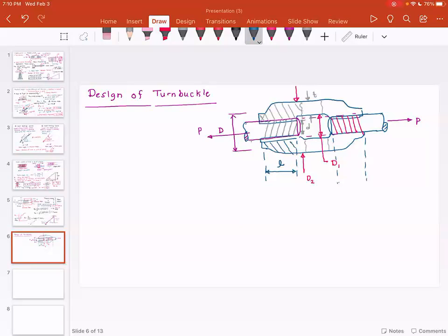But nowadays, all the designs are done on computer software. So you can create the 3D model, and then the software is capable of generating the design drawings. And that is the process that is currently used. So these dimensions that we find out from sort of the back of envelope calculation, they are verified using computer software or a finite element method.